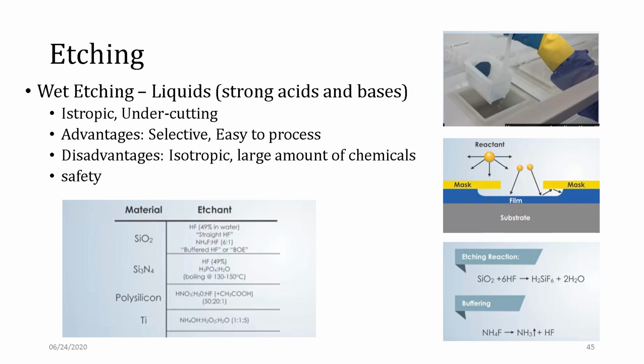It's no more silica. And sometimes, in order to expedite and increase the rate of this reaction, buffering agents like ammonium fluoride are used. So there have to be combinations of materials and combinations of etchants. Randomly things cannot be used, and these are chosen for a particular, say, photoresist.